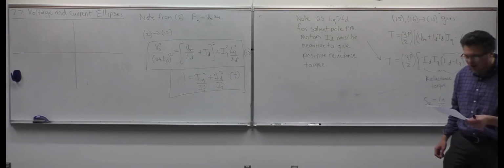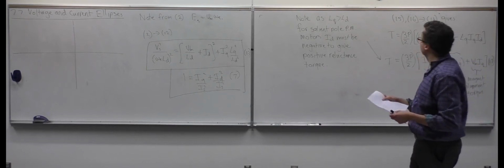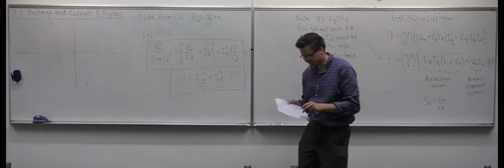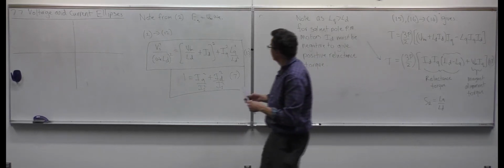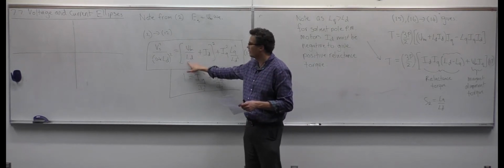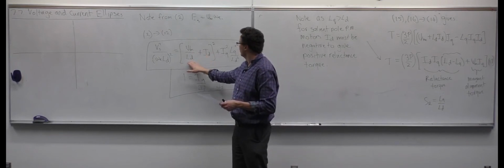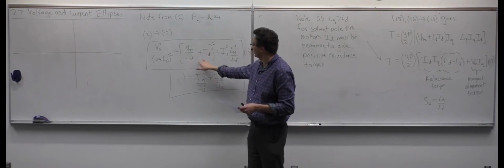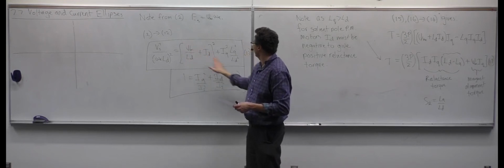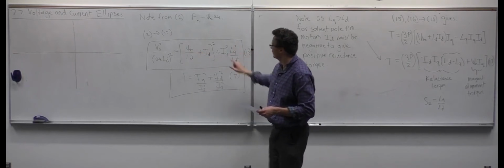Yeah. If you look at equation 11, there's a squared term, but it disappeared on equation 12. If you look at your notes, there should be a squared there. Sorry. Okay, so then this has got IQ squared and ID squared. There's also this term here, which is creating an offset in the ellipse. But it's an ellipse because, if you got rid of this term, the coefficient for the ID and the coefficient for the IQ would be different because of the LQ over LD squared part here.